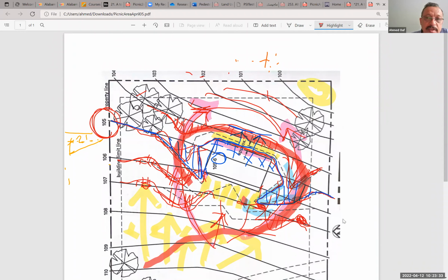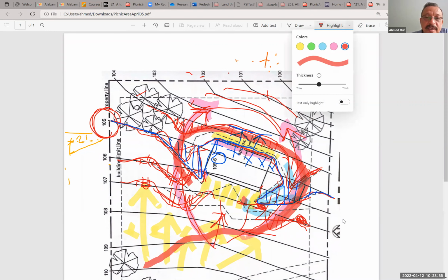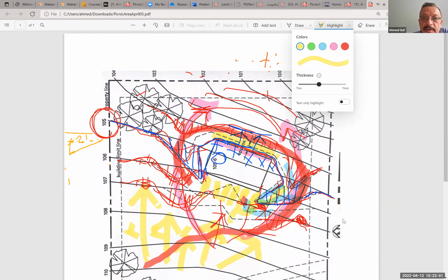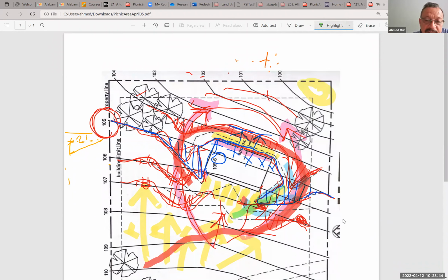So when the water, let me draw the water, if it collects anywhere going down here, oh, this is not really showing. Let me do it in green. If it goes like that, it goes by the pedestrian path to a specific point here where I might need a culvert or a pipe beneath the pedestrian path, or just collect water by the side of my sidewalk to a point where it seeps beneath the pedestrian path, or use some material that allows this water to go through without damaging my pedestrian path.